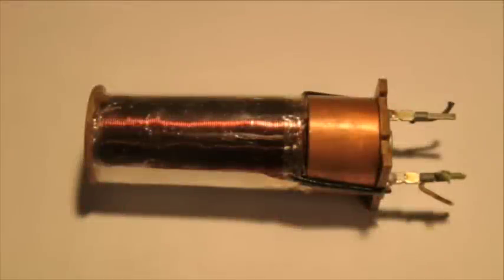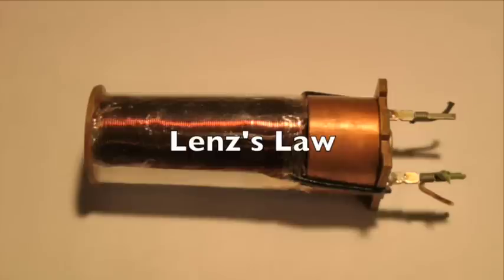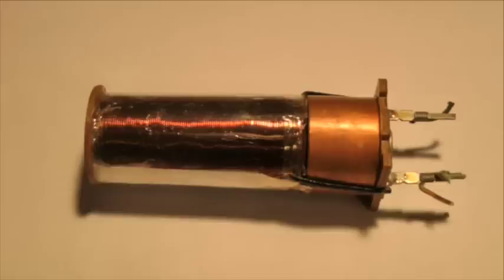Here you see a relay spool with its copper winding. On the heel end is a wide copper slug. This would provide the slow release feature. All 3 types of delaying devices work by using the principles of Lenz's law, in which the magnetic field induced in the delaying device opposes the collapsing magnetic field around the relay winding, and thereby slows this collapse.